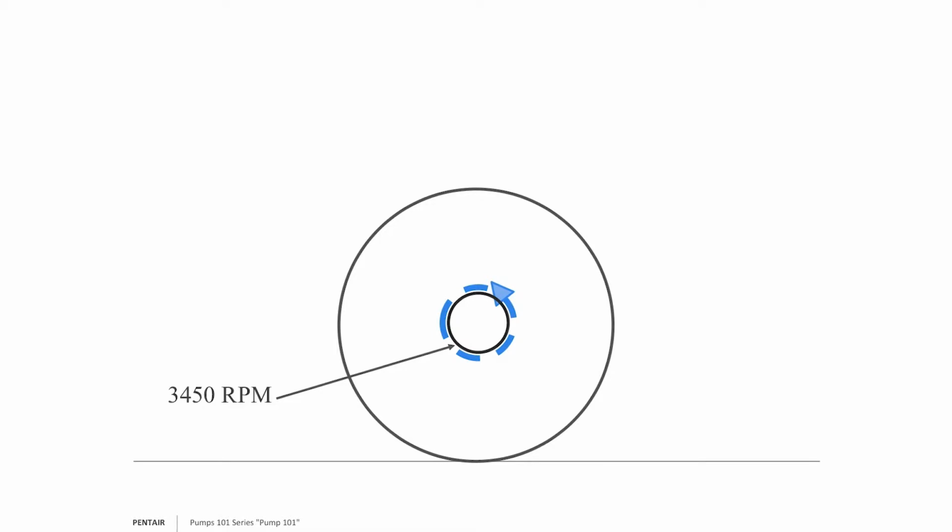To further explain this for you, to give you a better example, if you look at the eye of the impeller, okay, the eye of the impeller, say a cast iron impeller, it's going to spin counterclockwise when you look at it directly, okay? Now, more importantly, it's going to spin 3450 RPM. Now, I told you this is a cast iron impeller, so it has an outer peripheral, and that outer radius is larger, of course, than the inner eye of the impeller. Thus, it creates velocity, okay?